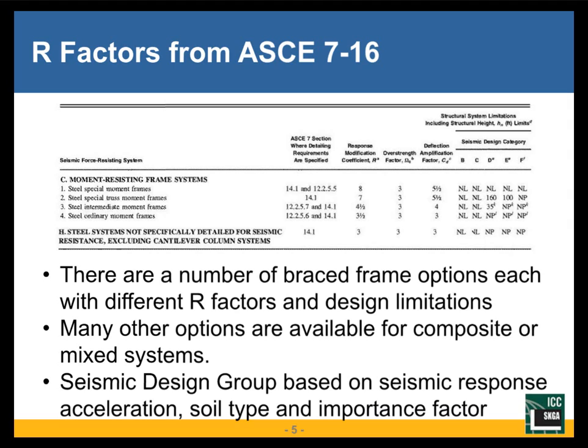And what you will see there is that some of the systems can be used without limit in the steel moment frames for the special moment resisting frame option. But others have limits or may not even be permitted for certain types of applications. If you're in zone A, B, and C, this might place you more likely to be in less seismically active zones of the United States, in the East and perhaps Midwest.